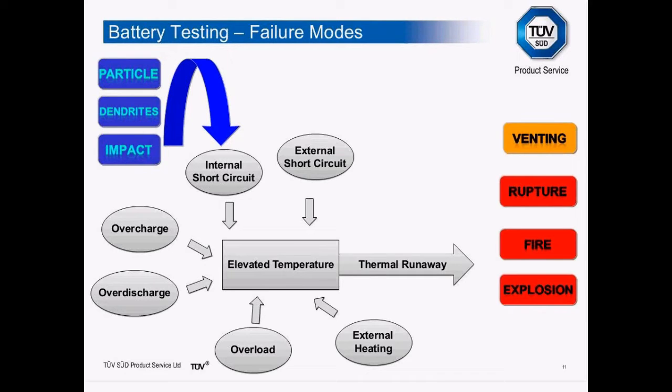Operating the battery in extreme external conditions, whether hot or cold, can also cause chemical imbalance, which can cause, for example, gas buildup, an increase in internal resistance, and an increase in internal temperature, which can finally result in thermal runaway.